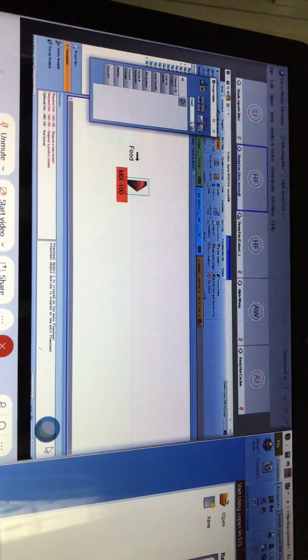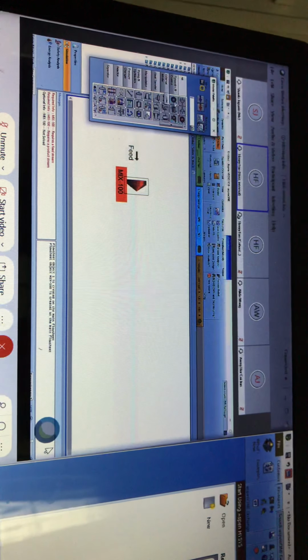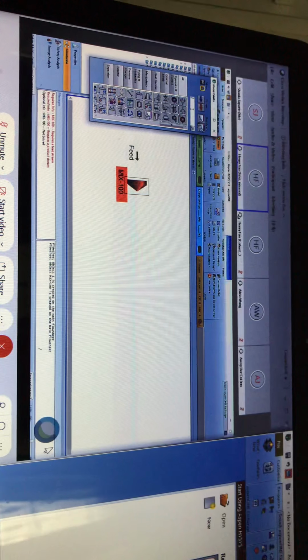When you're choosing the unit operations, either you search the name, or you search one by one through the symbols. It's quite tedious. You only need to search manually one by one if you do not know the names used in Hysys to define the unit operations, all the equipment.